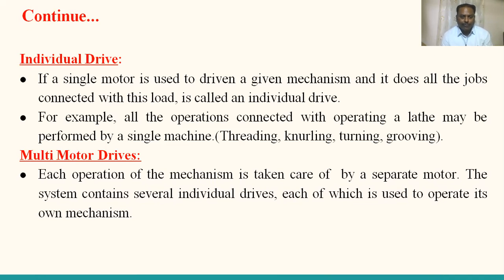For example, take a traveling crane. A traveling crane has different motors for different functionalities. For traveling from one place to another, one motor is used, whereas for lifting, another motor is used, and for some other purposes, other motors are there. So the drive consists of a number of motors, and each motor serves its own mechanism. That is the reason this is known as a multi-motor drive.